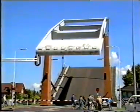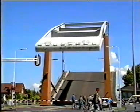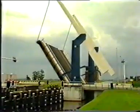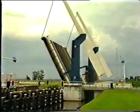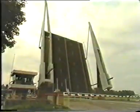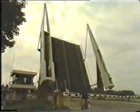The point of rotation is situated immediately adjacent to the column. However, the point of rotation may also be situated above the column. This would limit the angle of opening of the bridge severely. For this reason, an offset column is used. In bridges with an orthotropic deck, separate balance beams are used. The bracing is missing.